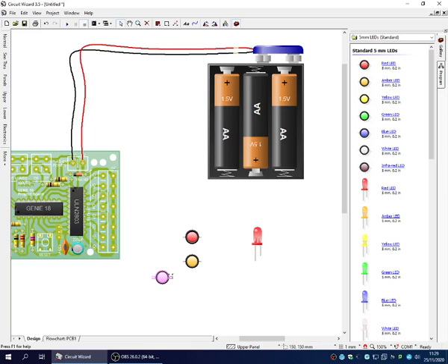If you move it, you can see you've got a kind of flat side on that side. Those of you who remember, the short stalk and the flat side are the barrier, so they don't let current flow from positive to negative through that direction. In other words, positive wants to be this side and it goes through to the negative. So just so you know, short one goes negative, long one goes positive, or in this case, the barrier, the flat side, goes to negative.